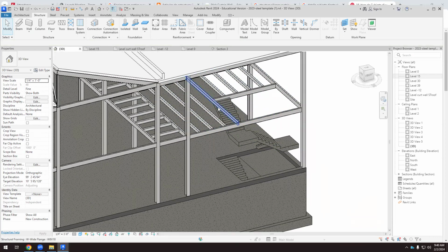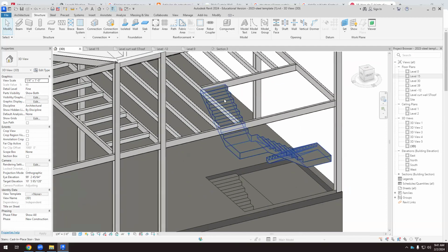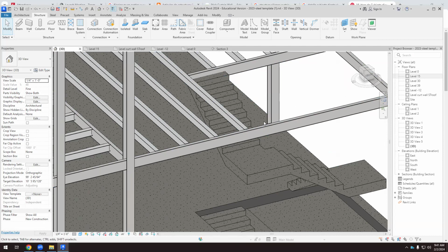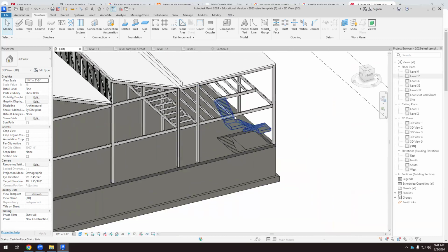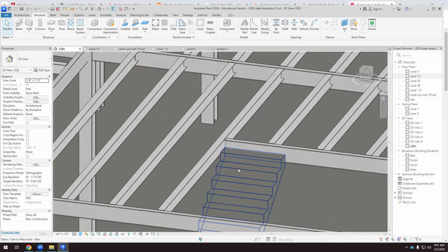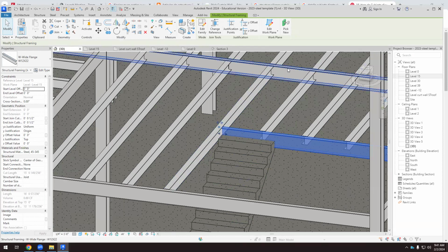And if I have the opening, I can go up and there's something structural limiting the opening. Can I make it better? I think so, because if we move this way, you see that I've created this beam, and now there's a hierarchy. The beam that connects columns is taller than the beams that made up the beam system. But now this beam is thicker than this one.